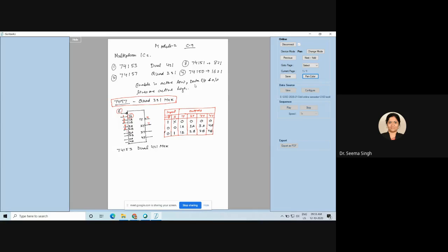So you will not see pin number 8 here. Directly we will have pin number 9 for the third IC, and pin number 10 and pin number 11 are your input. Why is this happening? Because when you construct an IC and embed things on your silicon chip, it has to come like this. You will get to know about these details in your higher semester. So that is why the third IC becomes ulta. 9 is the output, 10, 11 is your input.